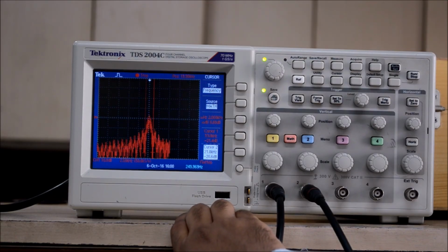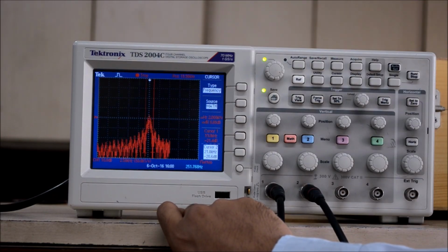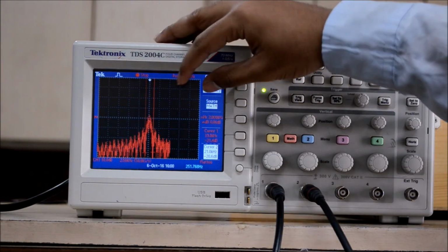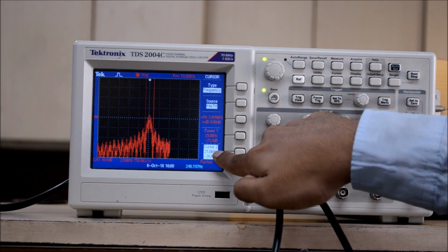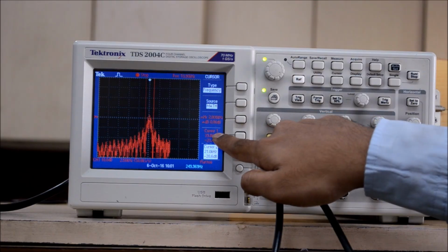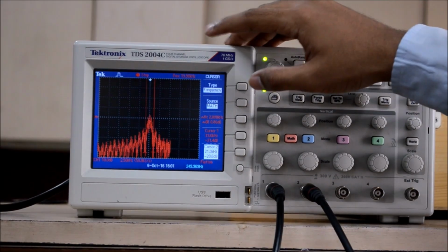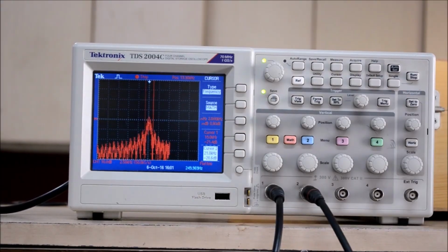Now, as we have studied in theory, the bandwidth of the BPSK signal is twice Fb. We observed earlier that the Fb, that is the frequency of the input digital pattern, was 1 kHz. So by using the formula 2Fb, that is 2 into 1 kilohertz, we will get 2 kilohertz bandwidth. To observe the bandwidth here, we subtract this frequency from this frequency. So 21 minus 19, that is 2 kilohertz bandwidth. So we can verify by both methods, by using the formula 2Fb and also by observing the spectrum and subtracting these two frequencies.